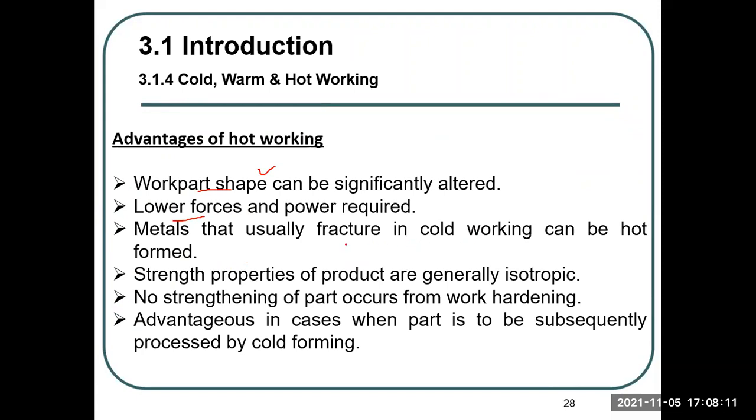If the material fractures very easily in cold work, you cannot use cold work; you can only use hot work. In this case the strength is isotropic and there's not much work hardening. Sometimes, after this, if people still want to increase the strength, you can do a little bit of cold work forming later. The good thing about hot work is you can get all sorts of shapes, compared with cold work.